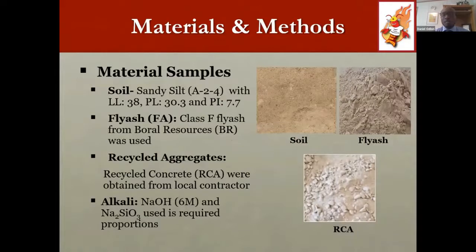The materials that we looked at for this research are a sandy silt soil sample, which was gotten from the Louisiana area. This was tested for physical properties like the liquid limit, the plastic limit, and the plasticity index. And we found the plasticity index to be 7.7.